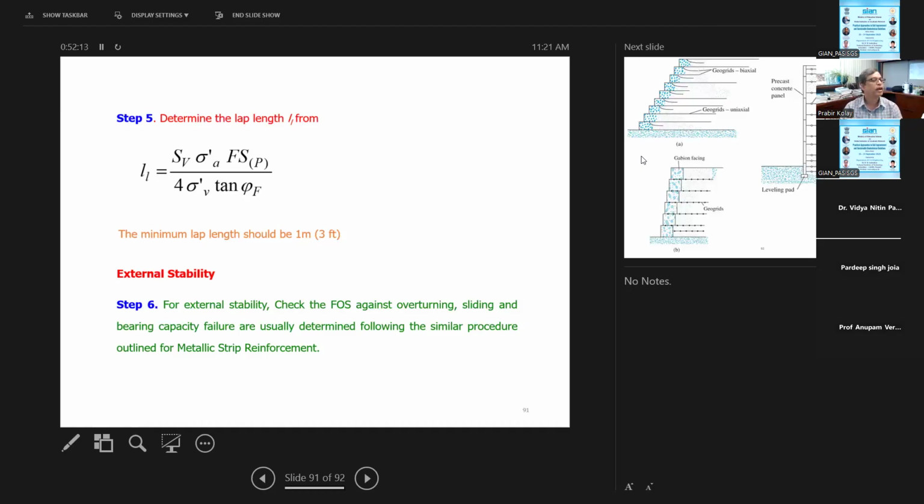Although I mentioned it in the slide, I think it's not very common. Depending on the availability of the material, people also use different types of fiber in the soil, such as high density polyethylene fiber and sisal fiber. There are a lot of fibers. Coconut coir fiber is also used as reinforcement. It is a disintegrating fiber. A similar type is the cotton geomat, but it's not easy to make. But I have seen some papers mention that.